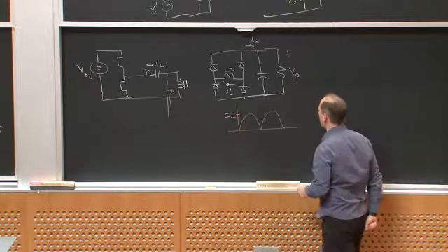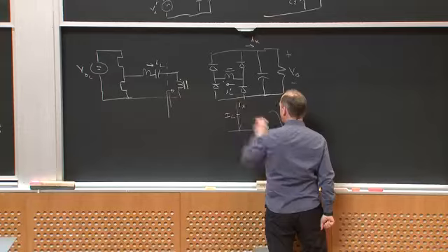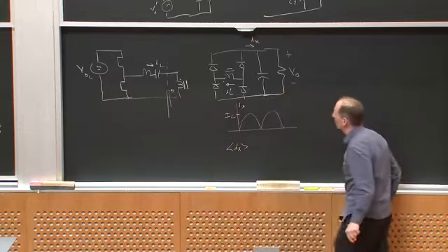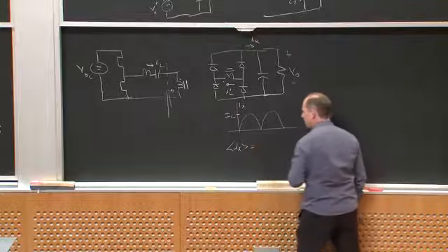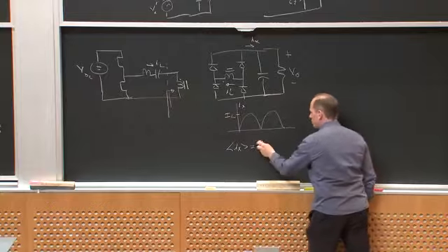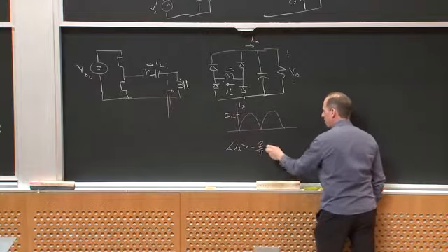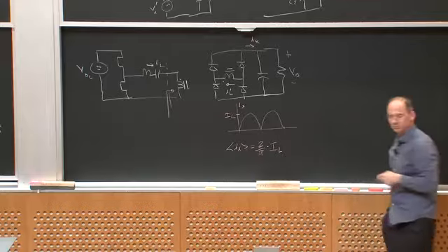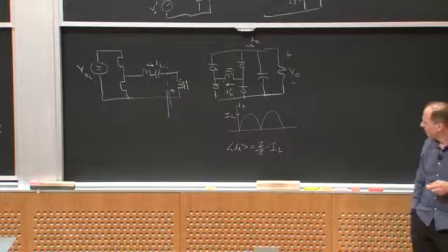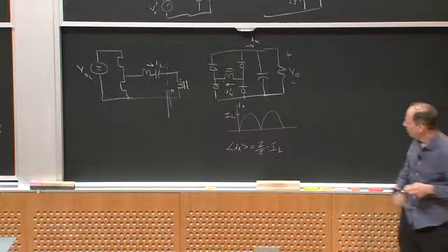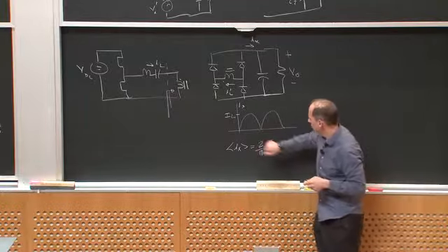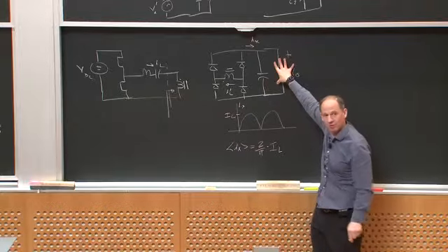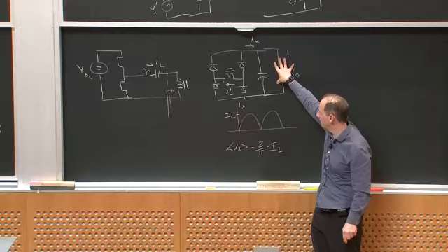So if I sub L has amplitude I sub L, then this just looks like a rectified version, right? The DC current, I'll call this IX, the average value of IX, and I'm running out of time so I don't have a chance to work this out, the average value of IX is simply going to be equal to 2 over pi times IL. So in some sense, what am I going to see here? I'm going to deliver some average current into my output. Okay.